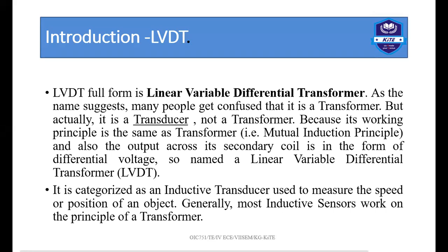A transducer will detect what is happening there, and it will convert one physical quantity to the other form, or its equivalent electrical quantity. One form of energy will be converted to its equivalent electrical quantity. Mechanical form will be converted to the electrical quantity. Let's see what is LVDT in detail.